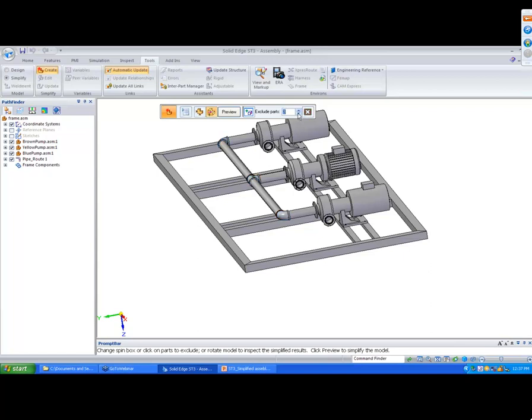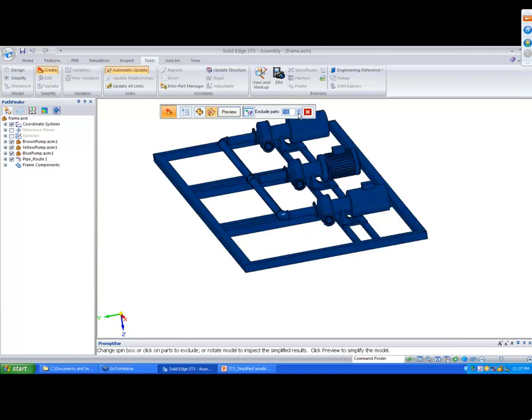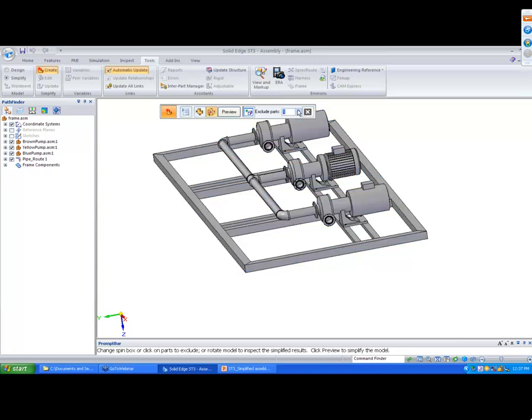I'm going to give you a small tip. There's a drop down here, and if you want to simplify by picking up the biggest part in the assembly, in this drop down, if you go down, it's going to start from the larger parts. So you can use this option in order to exclude parts. In this case, I'm going to just move this slider up, and also I can graphically select parts which I want to exclude. In this case, I'm going to select all these pipes and fittings.